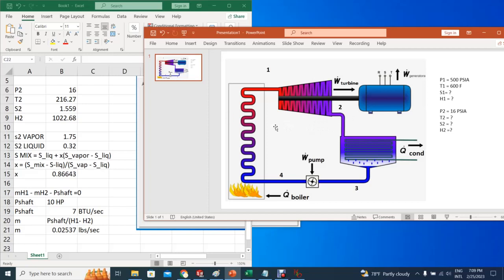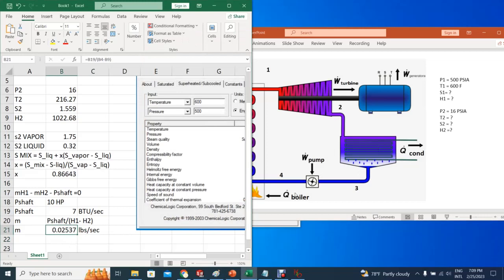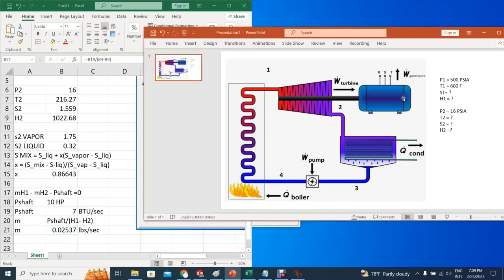So it's a different number, but again, it's just something that allows you to do a very quick calculation of where you are with this kind of Rankine cycle. Now, that's the mass flow. Period. That's it. You don't have to do anything else. Now, if we want to calculate very quickly the efficiency of the system, we need the amount of heat that we need here. And for that, it's as simple as trying to get condition 4. What will be the condition 4 for this system?